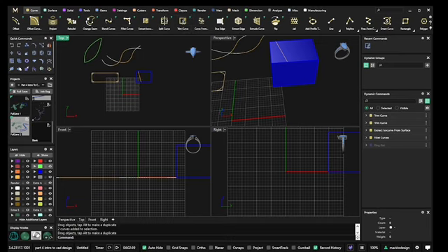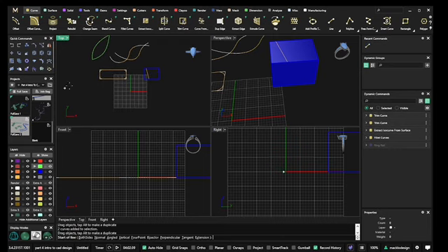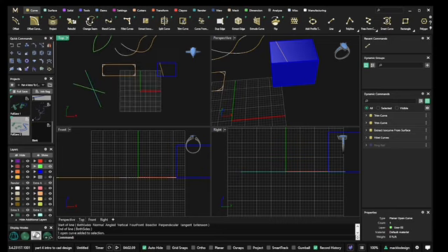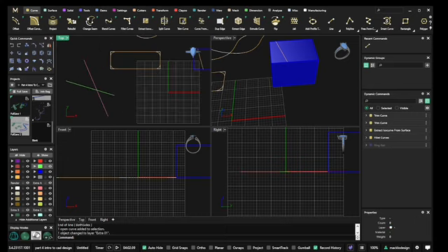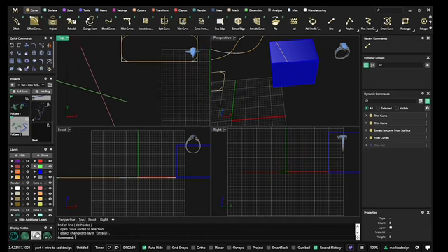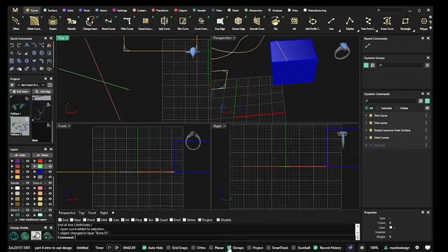All right, so now I want to do split curve. I'll do a straight one for that. There are times, I'm going to turn this a different color, there are times when you want to split a curve specifically at an intersection. So for this, we are going to come down here and make sure our O snaps are on.